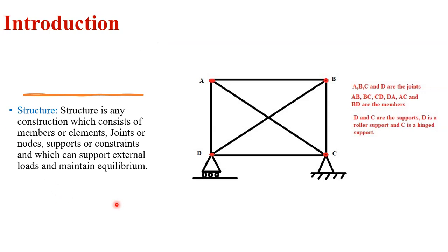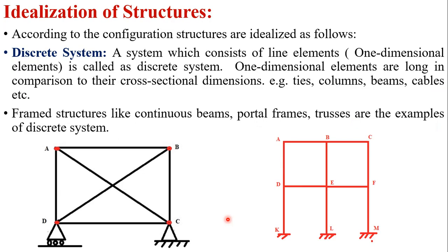And what is meant by analysis? Analysis means finding the internal forces as well as the support reactions which will develop in the structure because of the external load. Remember, the assembly or the construction must support the load and must maintain its equilibrium. Then it can serve the purpose and it can be called a structure.